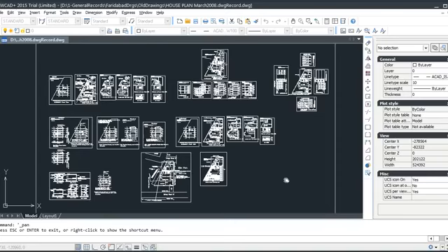Similarly, we have to check layouts of foundations. We have to apply and check steel, how it is. Then we have to provide concrete covers also, spacers we call them. Either you precast them at the site or you buy them. Well, I think precasting at the site is the best one. That's a professional one. And if it's binding wire, that's so that concrete goes into concrete.